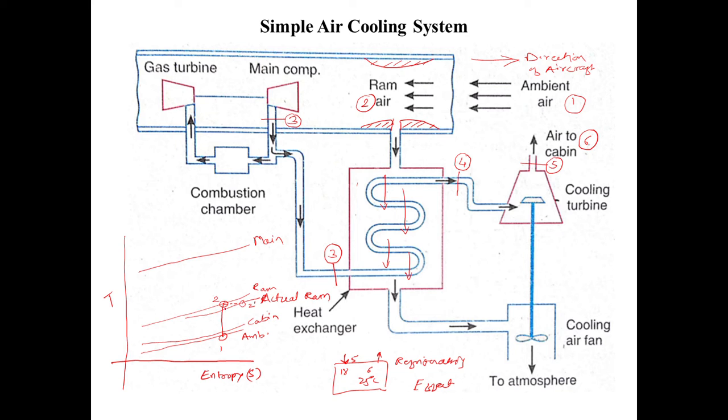Beyond that the temperature can't be increased, and that's why, though there is a loss in the pressure, the temperature will go up to the maximum temperature achieved in the ideal process, and hence you will not have the 2 dash point separately on the increased side. So this will be equal to the 2 only. So 2 and 2 dash will be the same. The temperature at point 2 and temperature at point 2 dash will be the same, and the actual ramming will be from 1 to 2 dash. So this is the actual ramming.